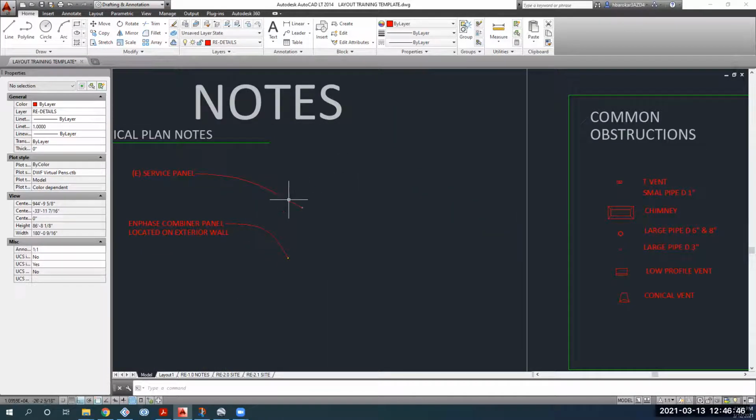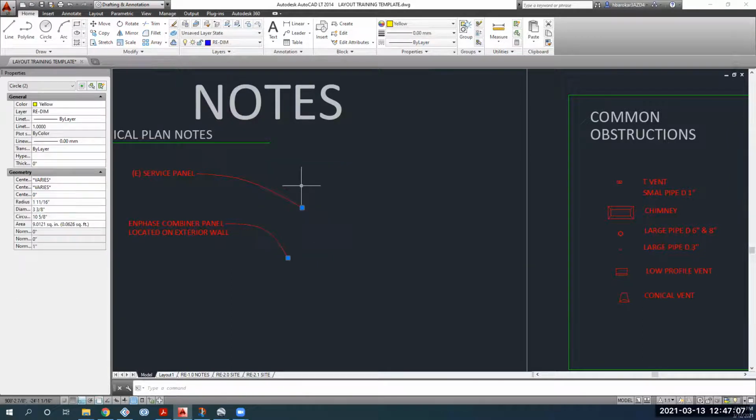In AutoCAD, the selection is a little weird, but it is also pretty helpful later on when you get good at it. When your cursor goes from left to right, it selects only the things that this rectangle completely covers.